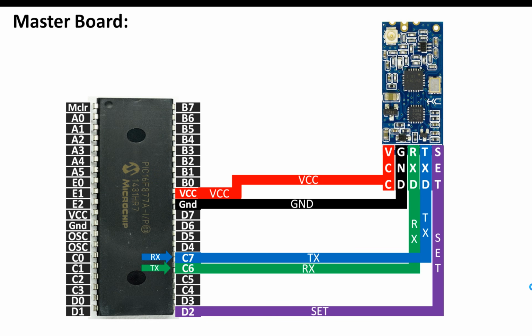So guys, this is our master board, and in the master board, as shown in the previous slide, we have a toggle button as well. But before that, we will also need a capacitor for the HC-12 module. This capacitor will regulate the voltage, because whenever the communication is done, it draws 100 milliampere of current at max whenever it is transmitting the data. So at that time, there is a possibility that the voltage may fall, causing the communication to break down.